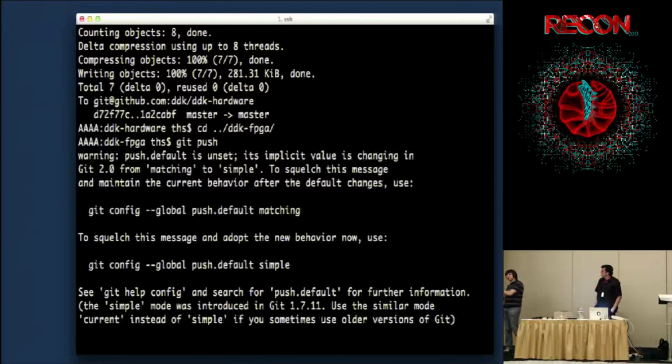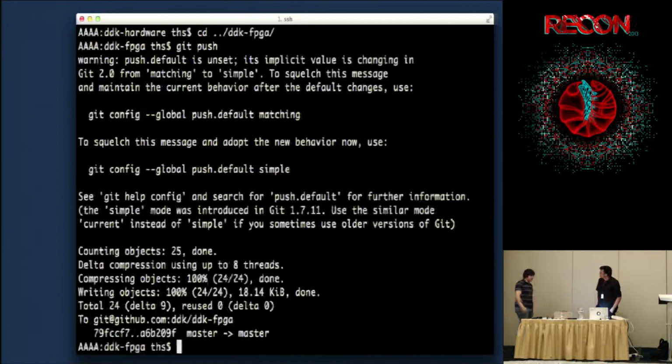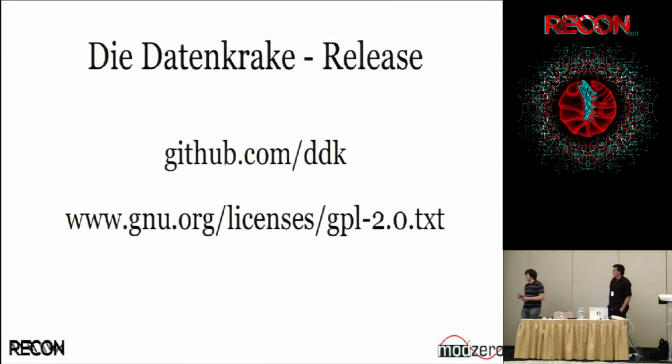By the way, I guess we also forgot to mention it. The FPGA tools that we're using, they're not open source, but the tools are completely free. And Microsemi actually has one of the best tool chains out there, if you ask me, because they use the tools that you would use if you tomorrow start at an ASIC design shop. You would use ModelSim, Synopsys Simplify, and the place and route tool is always vendor specific, but it's the industry standard tools that you get for free from Microsemi. If you ask me, that's awesome. So you get nice tools from them for free. That was one of the main reasons why we chose them.